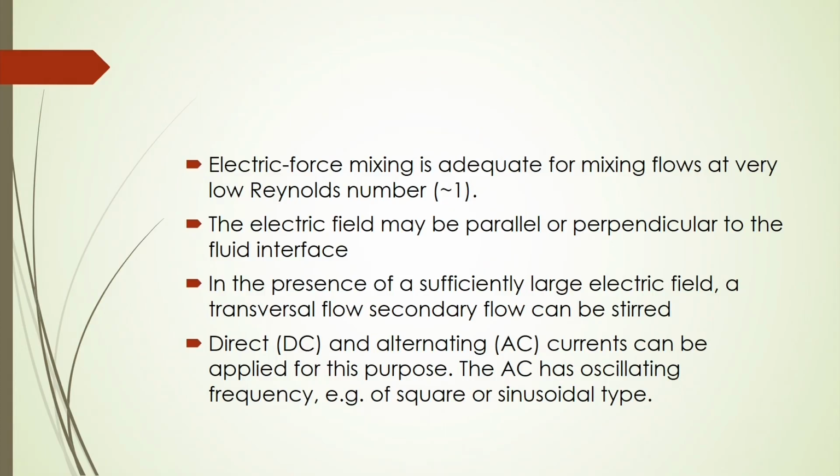Electric force mixing is adequate for mixing flows at very low Reynolds number, and the field may be parallel or perpendicular to the fluid interfaces. In the presence of a sufficiently large electric field, a transversal secondary flow can be steered.